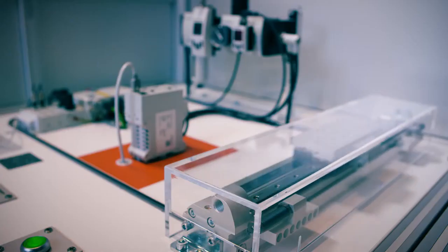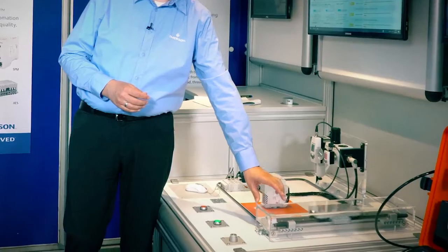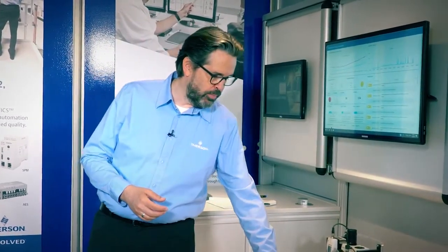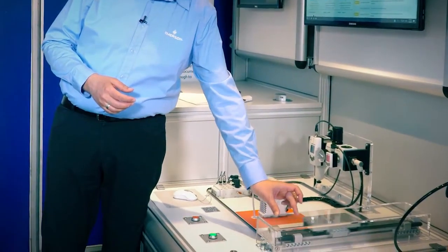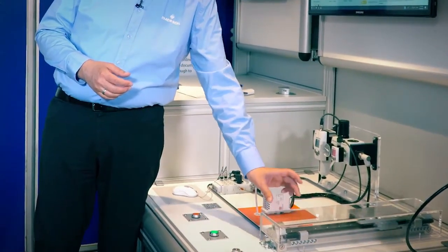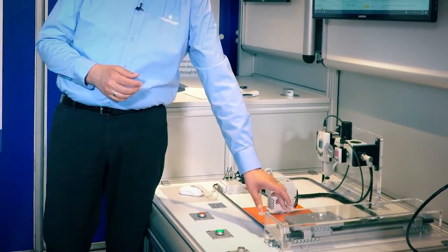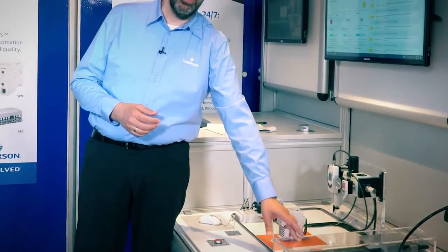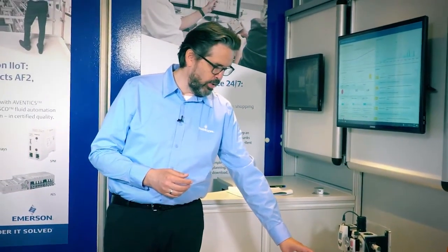Another lifetime indication we can give is for the shock absorbers at the cylinder. The shock absorber over the lifetime is getting more and more inefficient. That means it is a wear part which usually has to be changed in the maintenance cycle of the machine. This also usually means that it's exchanged too early because obviously it hasn't failed yet. What we can do now is measure the efficiency of the shock absorber during the lifetime of the machine by measuring the time it takes the shock absorber to actually stop the cylinder. The shorter this time gets, the less effective the shock absorber gets, and we monitor that for the whole time and give you an indication when this efficiency is actually decreasing.